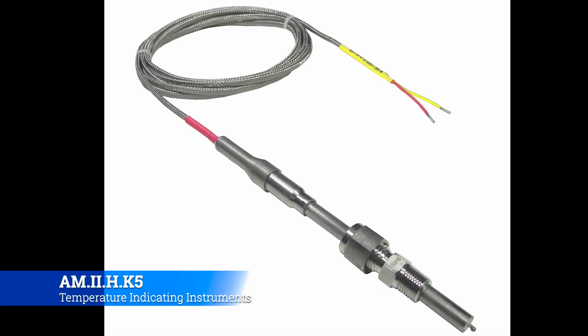And so what you'll end up having is a probe that will go into an oil bath of some variety, or into a gas flow like on an EGT, and then it'll simply run an electrical line back to a sensing unit. All that sensing unit basically does is say, hey, look, I'm putting 1 volt in there, and I'm seeing this kind of reading on the electrical side, so therefore the temperature must be this. And that's what it's displaying inside the cockpit. And so these are really, really common.